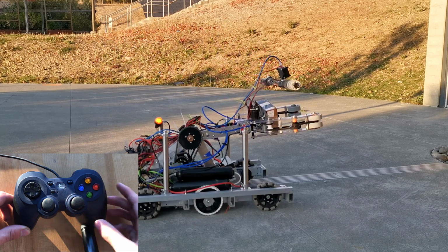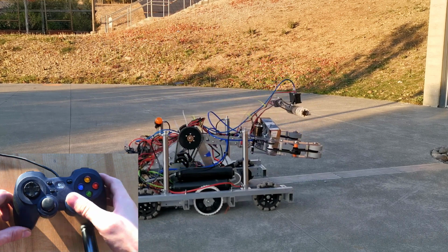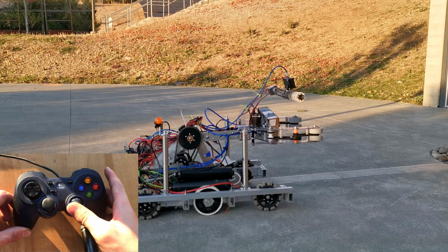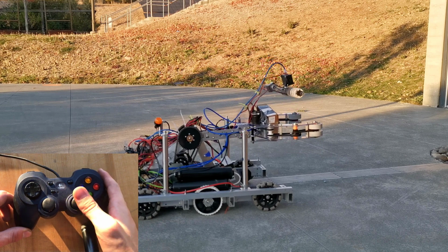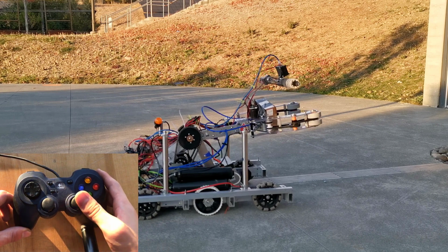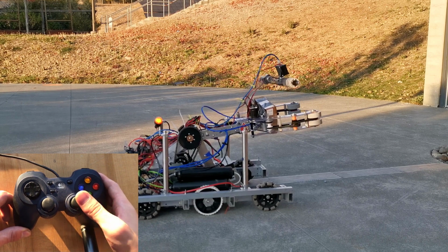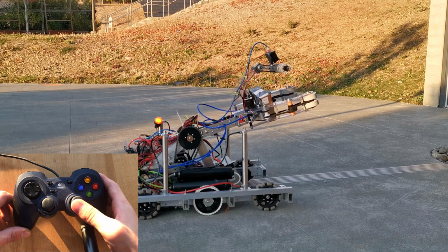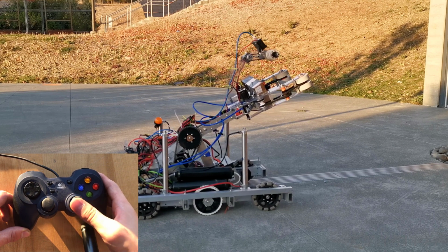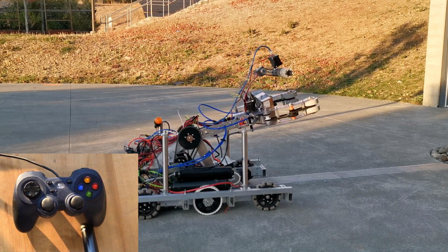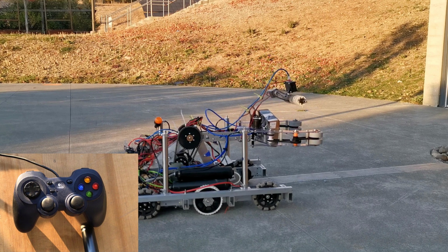Second, the communication lag between the driver and the robot can make the arm not very responsive and frustrating to control. Third, it would take a long time to tweak the joystick until the arm gets to our desired angle. Fourth, after the arm reaches our desired angle, if we release the joystick, the arm may still slowly fall down again.